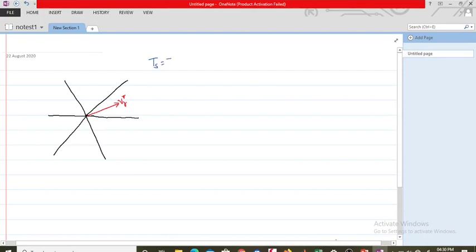This sampling time TS is approximately equal to 10 microseconds, which is very small compared to 20 milliseconds, or we can say, obviously, 50 hertz. Okay, because 50 hertz is required, and this 10 microseconds is very much less than the 50 hertz time signal.